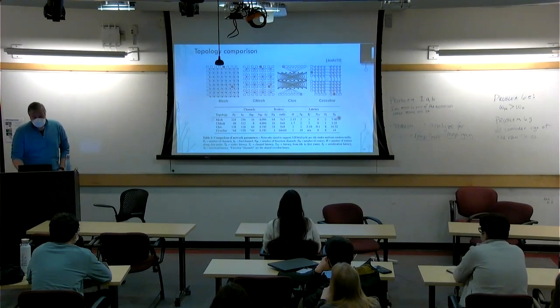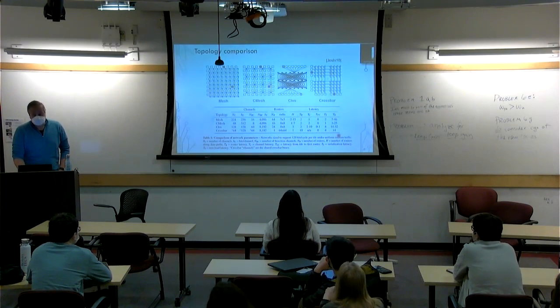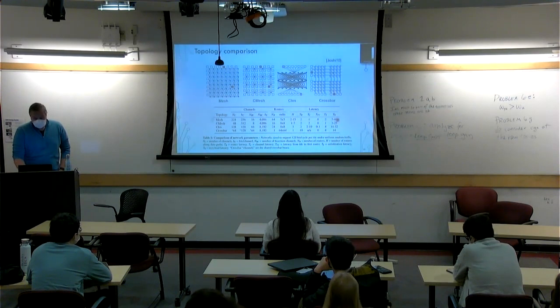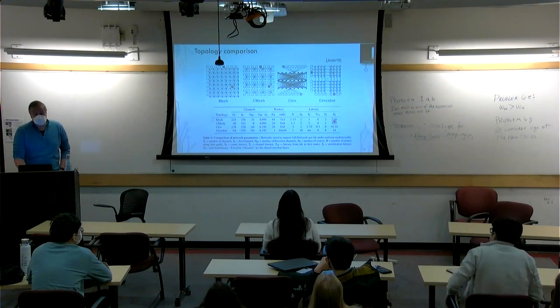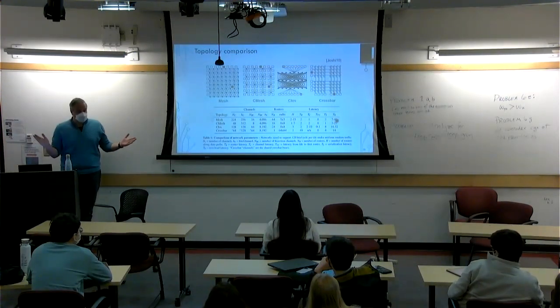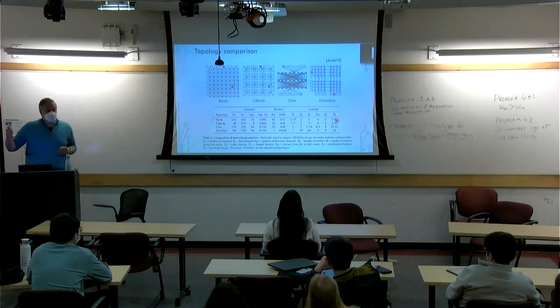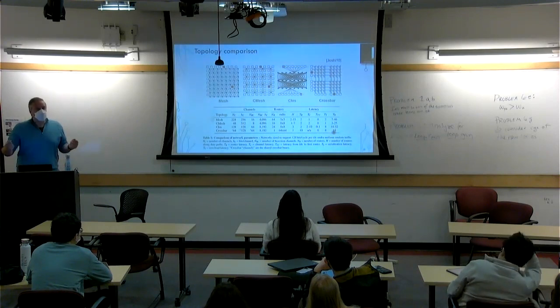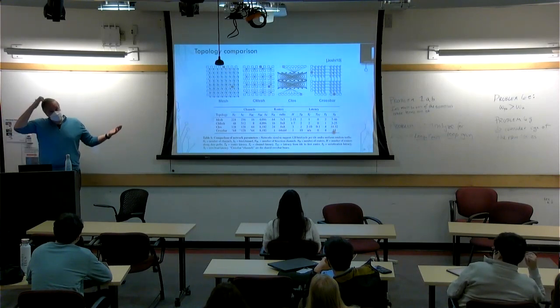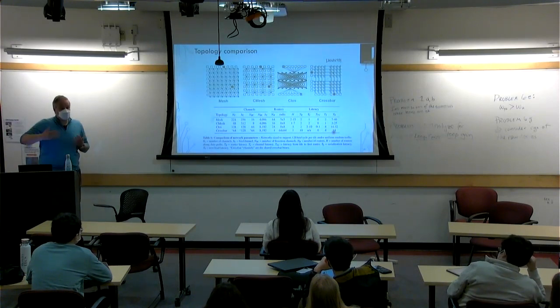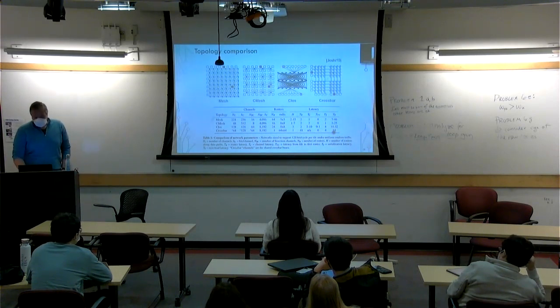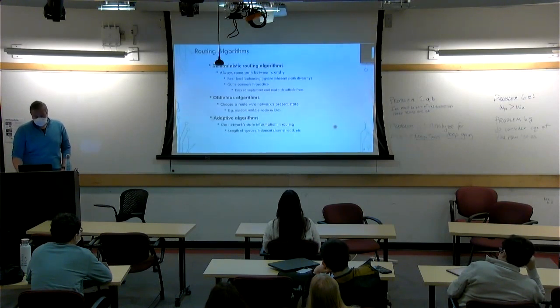And then, of course, my latencies will be essentially larger. And you see here that mesh has the widest spread of the latencies, depending on where you're really going. In the worst case, you're 46. Fastest case, 7. Pretty good. Whereas crossbar, it's actually 1 hop, but this is a 64 radix crossbar, so it needs a lot of stages to just get across that size crossbar, and its logic, right? And then Clos has a narrower distribution and things like that. Okay.